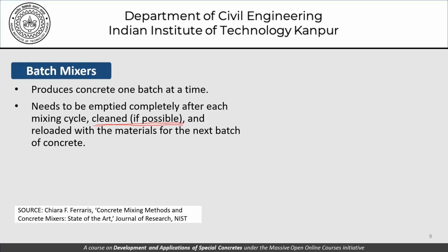That takes us to the discussion of priming the equipment. That is, we make sure at the start of the mixing cycle that we mix a batch of concrete which is thrown away, which is similar to the batches of concrete that we use subsequently, and therefore the batch we throw away leaves behind in the mixer some mortar or whatever it is, so that for subsequent batches, the batches actually contain the kind of concrete ingredients that is designed for.